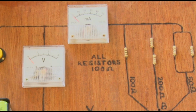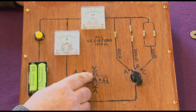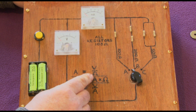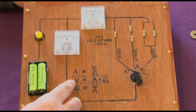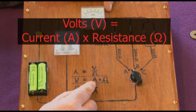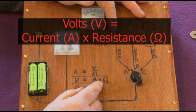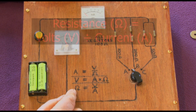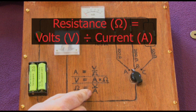And that's Ohm's law. The idea that if we've got two of the three values, the current, the voltage and the resistance, we can work out the third. That's how we work out the current. If we want to work out the number of volts, we take the current in amps, not milliamps, and multiply it by the resistance. That will give us the volts. Or if we want to know the number of ohms, the resistance, we can take the voltage and divide it by the current.